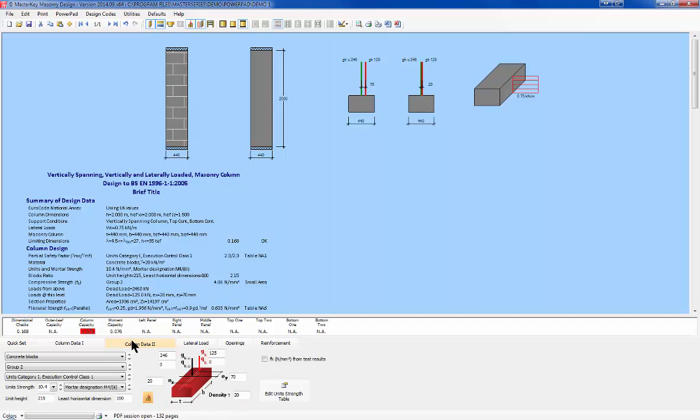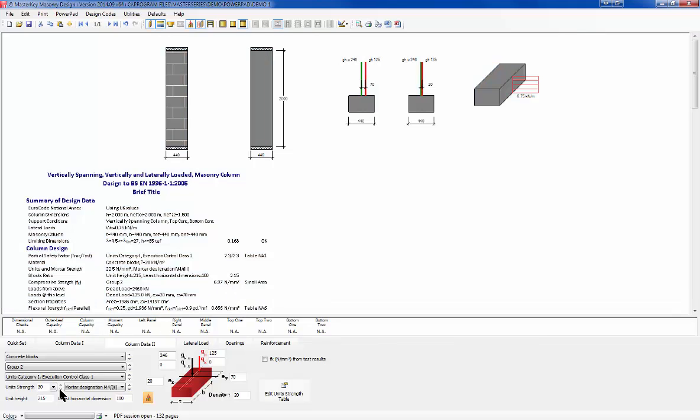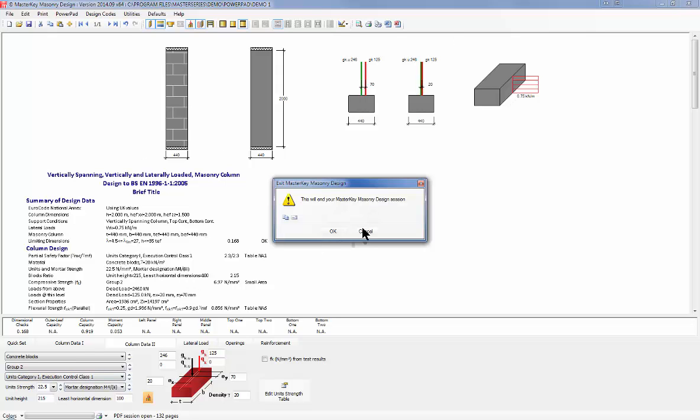other data, such as what is our categories, what is our strength. So let's get up there. If we use 22 or 25 or 30 Newton units masonry, away we go. We can resist that loading and we're happy. So that's the masonry. Very straightforward, very simple.